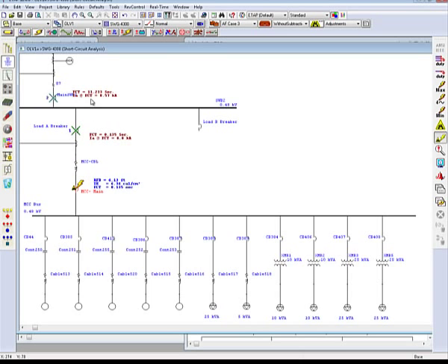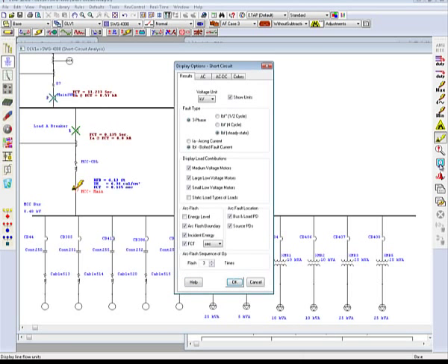One other feature that you can have for the arc flash sequence of operation is control over the flashing of the events. So you can either increase the speed of the flashing or pause it altogether. You can do so by entering the display options on the right hand side toolbar and locating the arc flash sequence of operation section here at the bottom.